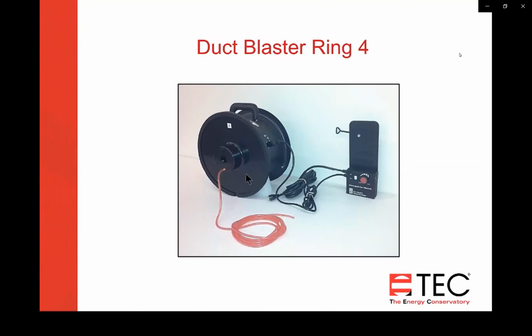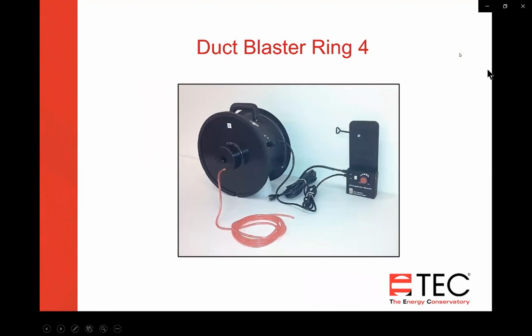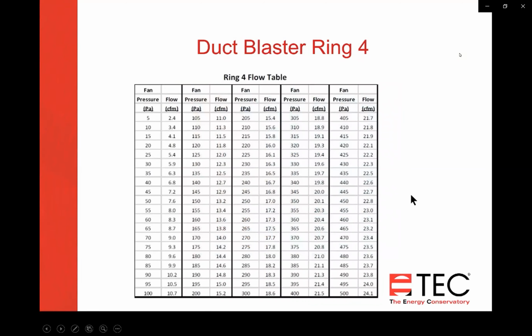If you've got a DG700, you don't have a ring 4 option, and you'll need to use this flow chart. You'll connect to the tap on ring 4, and then you'll connect that to the input on channel B. Channel A will go to the ductwork like you normally would, and you need to get channel A up to 25, just like you would with any duct leakage test.